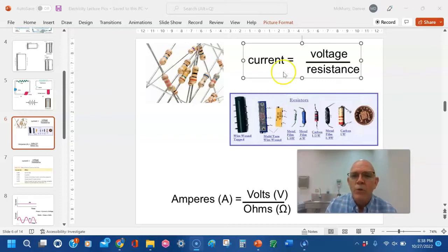Now, good question, real quick. Is it more dangerous to get high current or high voltage? Okay, well, technically, it's the amount of current that kills you. Okay, but obviously, since the more voltage you have, it's a lot more dangerous to be around high voltage wires. You see signs that say caution, high voltage. Okay, because if you have a high voltage, then it's more likely. If you have low voltage, obviously you can't have too much current, probably, if there's any resistance at all. But it depends on the amount of resistance.